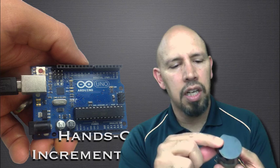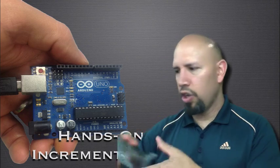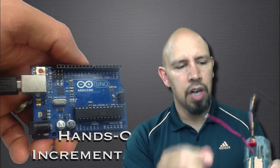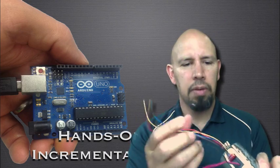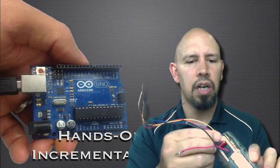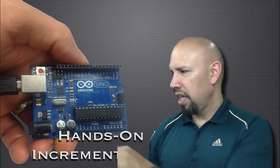In this case, the cover is not for lighting, it's for keeping dust out. Okay. Here is another example of a larger motor. This one actually has an encoder in there, an optical encoder. It's very common for an optical encoder to have 4 wires. Again, 1 for power, 1 for ground, and then 2 for the signals. Okay, so that's what those are.